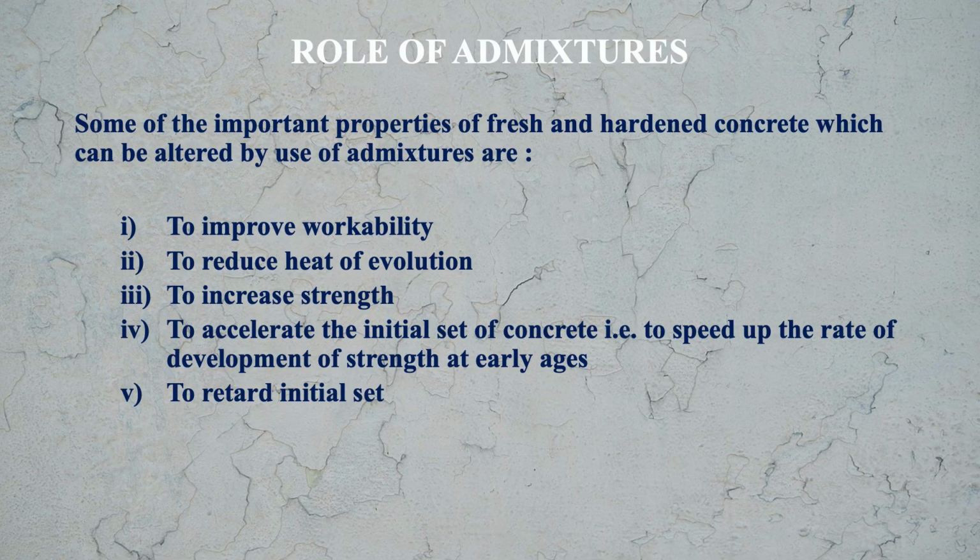Then in some conditions we do the opposite also by using admixtures, meaning we retard the initial setting time of the concrete, because we want to use the concrete in such conditions that within a certain time it is not possible to place and compact the concrete. So in such situations we retard the initial setting time by using the admixtures.